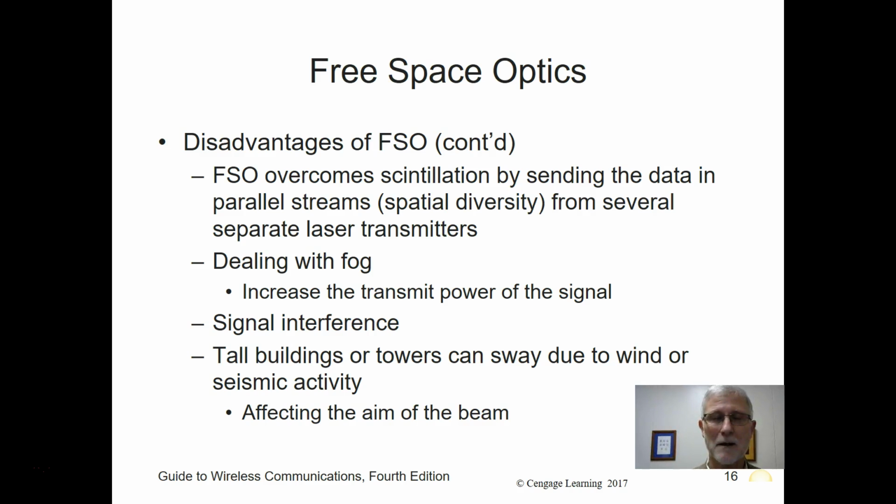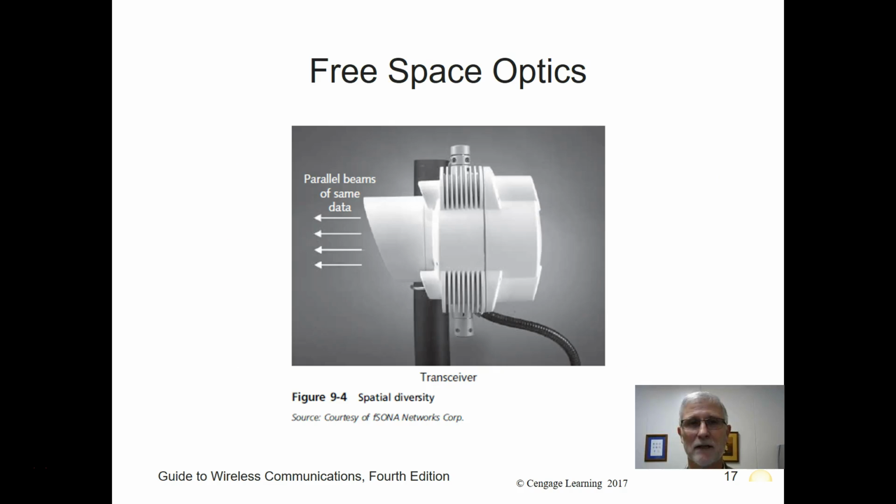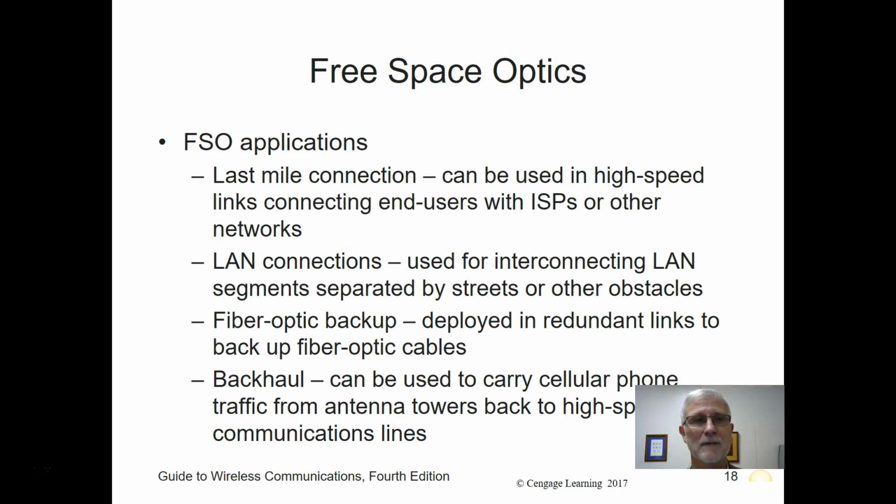I don't know if you've ever been on top of the Sears Tower or something like that on a windy day. It'll actually move and you can feel it. But if you haven't accounted for that movement in that free space optic design, it may affect that beam and connectivity. Just gives you a different idea. Now, applications: last mile connections, local area network connections, fiber optic backup. It's great as a redundant link.